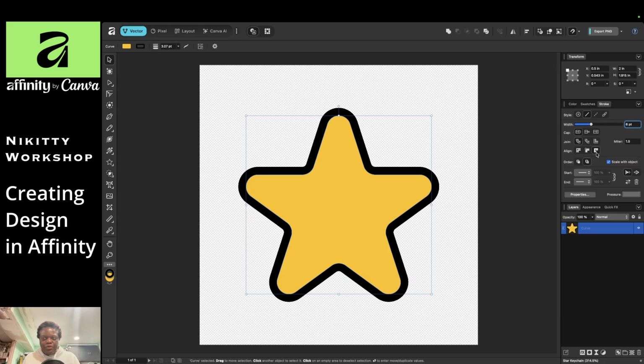Yeah, that's all we're gonna mess with here. So we have our stroke. Like I mentioned, I put it on the outside, so I have to worry about subtracting and all of that to get it into the design. The thing is, you don't want each different color element to overlap when you're doing the 3D print, and it's gonna cause an error because it's like you're printing over existing space. Each color needs to be in its own space when you're 3D printing. So